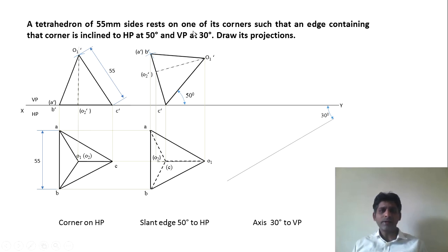So we have true inclination and apparent length, and apparent length cannot be plotted on true inclination. To plot this apparent length, we need the apparent inclination. So in this case, we have to use locus method to obtain the apparent inclination.